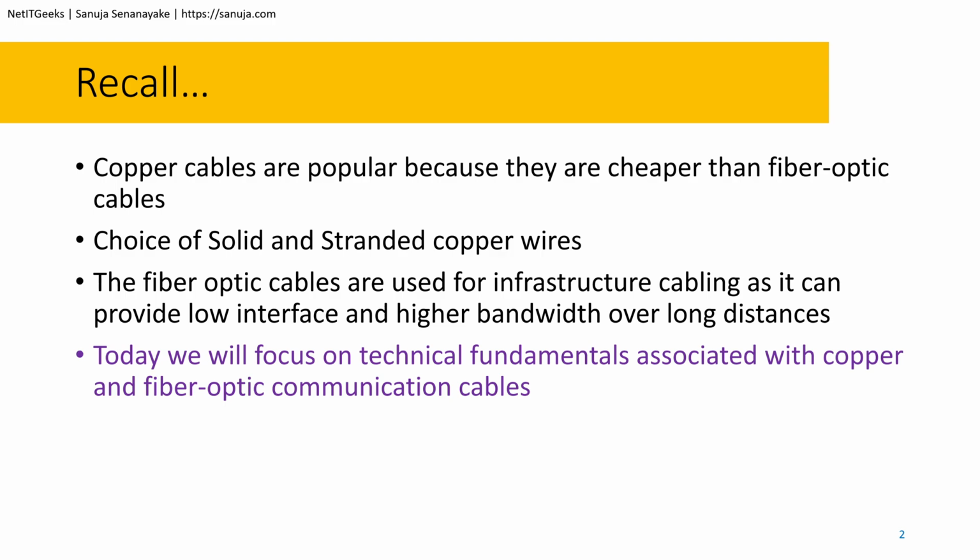Recall from our previous lecture, I said solid core copper cables are typically used in infrastructure settings where the cable is going in the ceiling tiles, for example, or behind the walls, as opposed to stranded cables, which are more flexible and used for patch cables, etc.